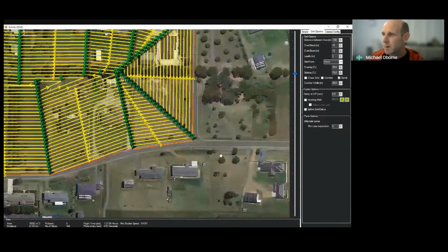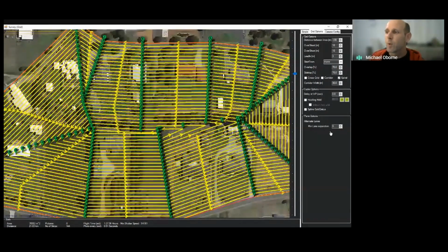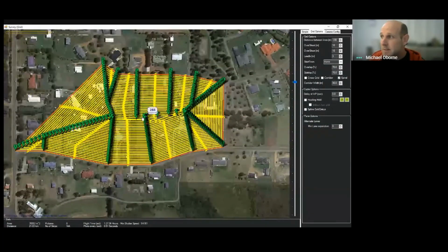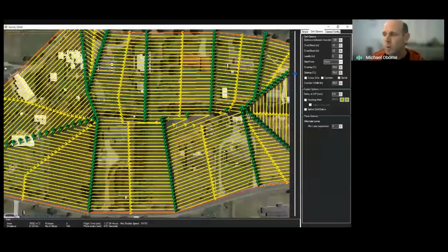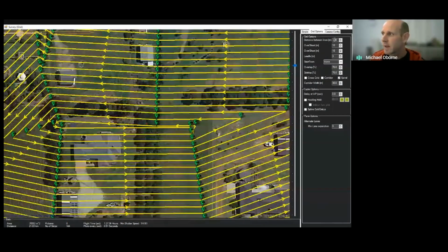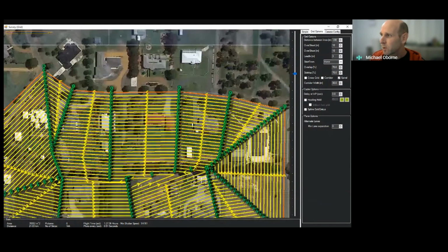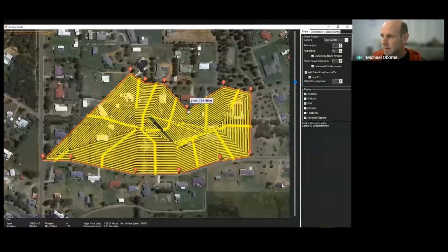So this is a spiral. The most common use of this is for rovers, for something like a lawnmower or for spraying, or some other purpose. Obviously this can be used with a plane or a quadcopter, but the original intent was for a rover driving along the entire area. Again, 3.8 meters between lines here, and it just drives around. Like everything you saw before, you can drag the markers around the edge if you want to, and it will dynamically create stuff.